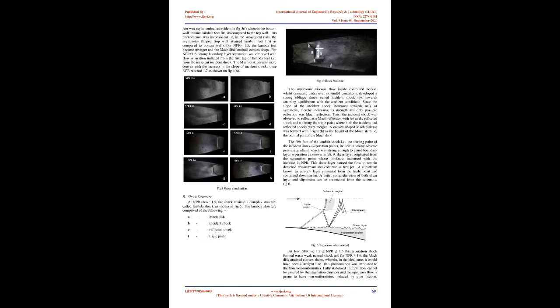The nozzle profiles were mounted onto the base plate using Allen screws. In order to make the test section transparent for Schlieren visualization, the mild steel base plates were provisioned with 2 slots for holding the glass window. 2 extra clear glasses of 12 mm thickness were tight-fitted in these slots. The nozzle base plate assembly was mounted onto the stagnation chamber using a flange made of mild steel. Fig. 2: Schematic of blow-down tunnel setup.